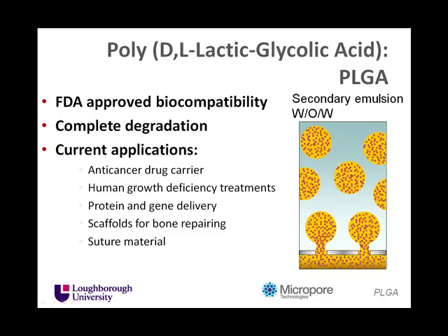So what have we got here? We've got this usual Micropore style membrane, straight through membrane. We have a primary emulsion which is illustrated in this sort of purpley colour inside the yellow. So the yellow here represents an oil phase. That purpley colour is in fact an aqueous phase inside the oil phase. So this is a primary emulsion, and we're using the Micropore membrane emulsification system to create the secondary emulsion. So this is literally a water in oil in water emulsion, or WOW emulsion.